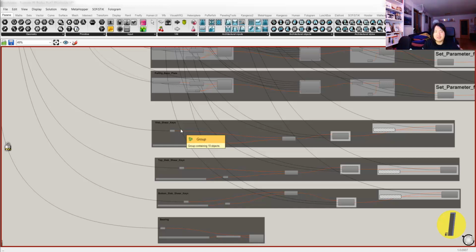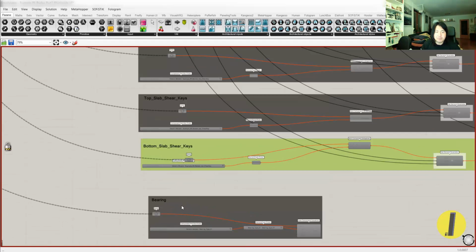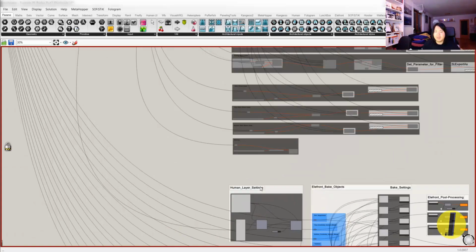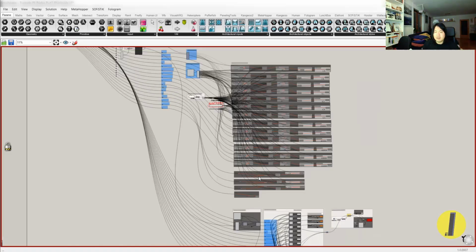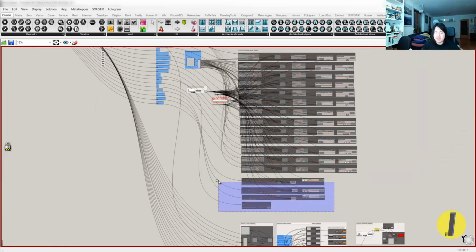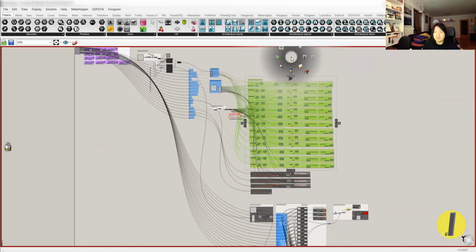I'll use the IFC 2x3 model view definition, and for that we don't have a bridge category. I think buildingSMART is working hard to provide an infrastructure category in the future in IFC5, but unfortunately we cannot use the infrastructure category or IFC entities, so we're going to convert them as building entities. So this is a shear key and the bearing. I leave the shear keys and bearing part at the moment as it is, and let me enable all this